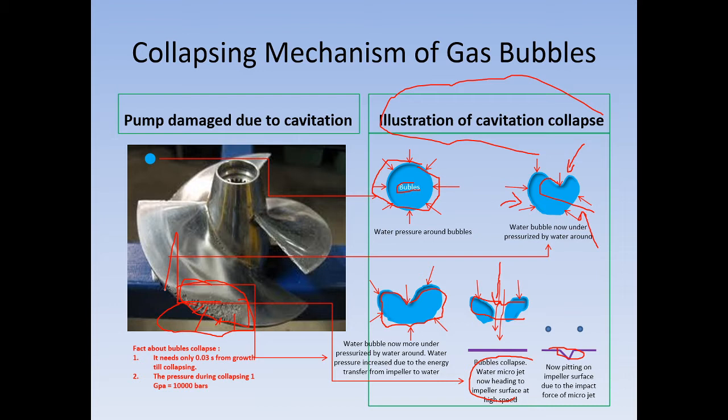Usually when cavitation happens, the sound is like marbles, clack, clack, clack, like that. I witnessed it myself on the test rig. So you can notice that cavitation is already going on without seeing the instrument.